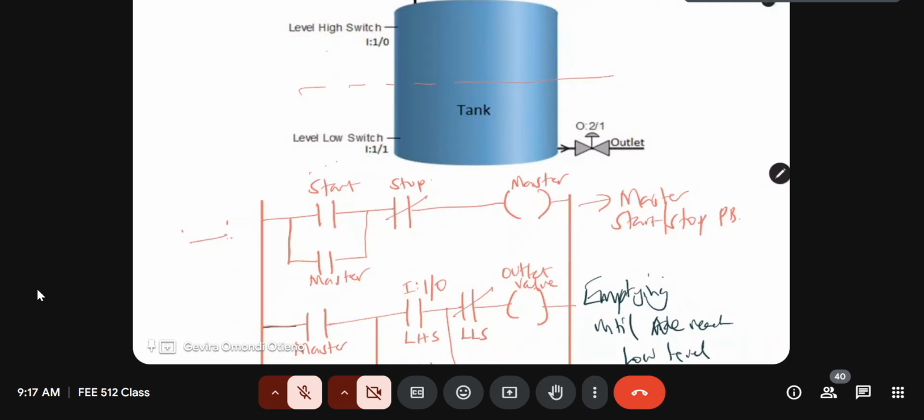You could incorporate, like you say, other switches that are not physical. For example, if we had a sensor that is able to scan through the entire length, or in this case the entire height of the tank, so it sends a beam through the entire length of the tank, and then you can detect at what level the water is.